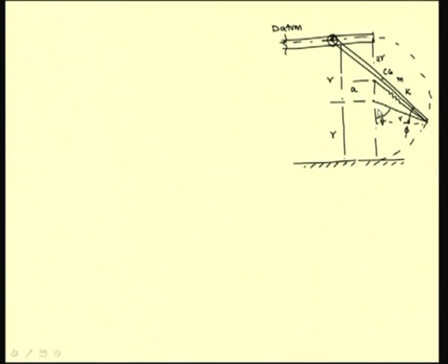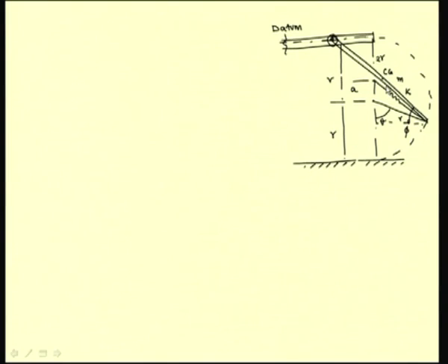So, we are interested to know that when this theta is equal to 0, or for this door in the completely closed position, the door is having a stable equilibrium. So, let us fix this as our datum, that is the top slot in which this roller slides as our datum, and measure the CG of this door with respect to the datum.